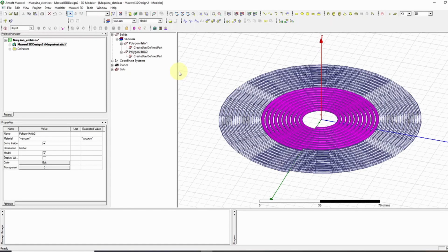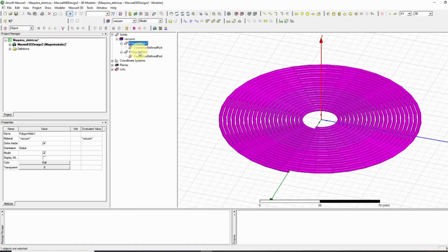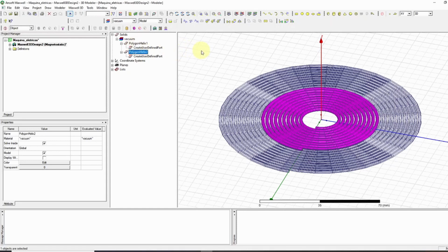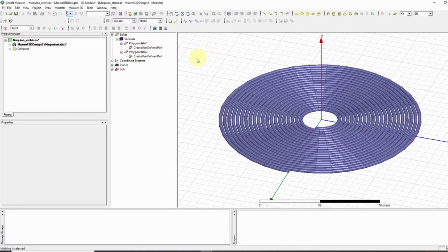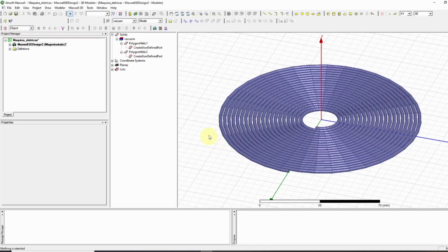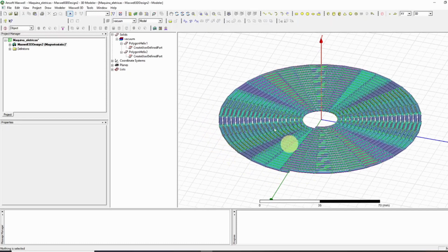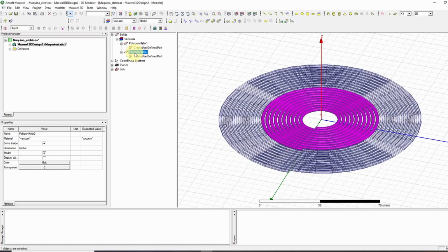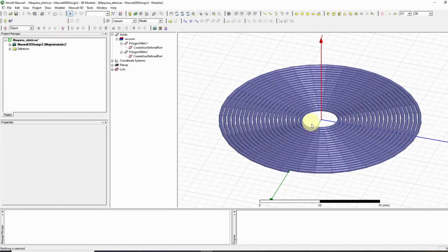Okay, so here we have the coils created. We have the 2 coils here, they're intersecting one another. So if you see in this normal view, you will only see one coil because the other one is right here, intersecting with the other one. And since they have the same parameters, except the number of turns, they're going to look like one, they're not different in any other way. So what I'm going to do now is extrude it in the z direction.